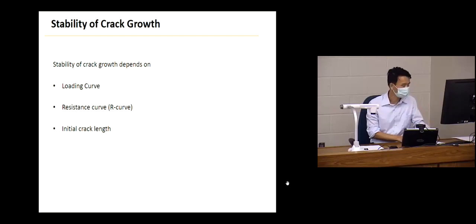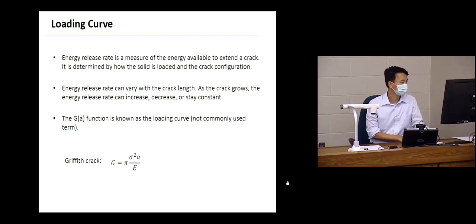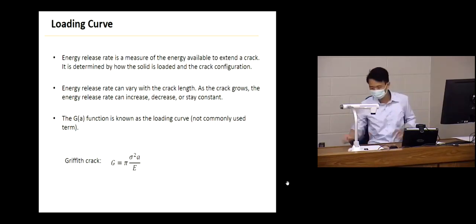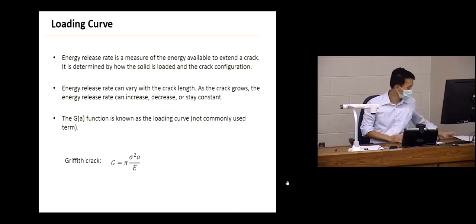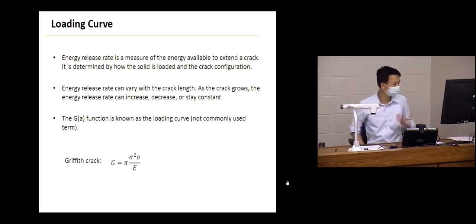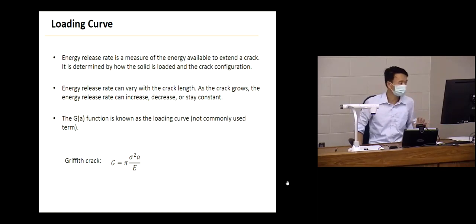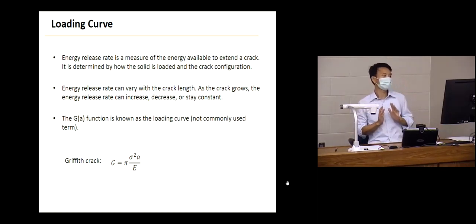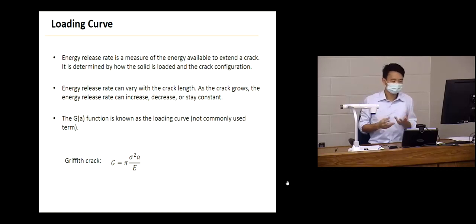So what is the loading curve? This is not a very commonly used term, but I like to use it because it differentiates from the resistance curve. The loading curve is related to the energy release rate, right? Think about the energy release rate and the fracture process. Energy release rate is always related to how we load the material.